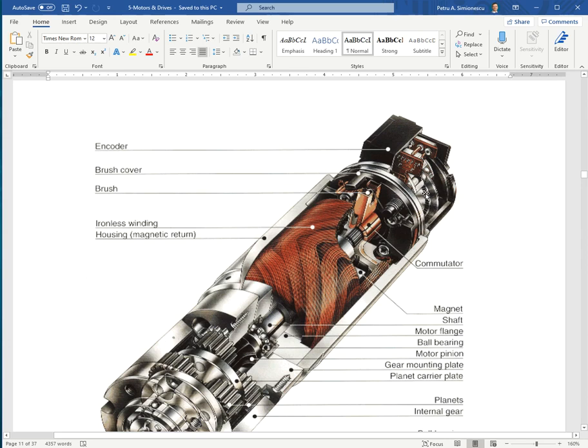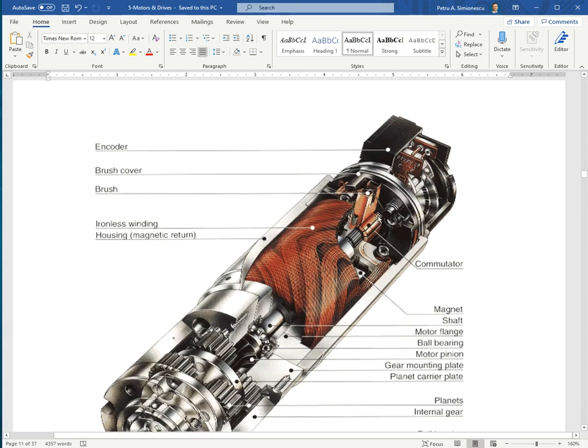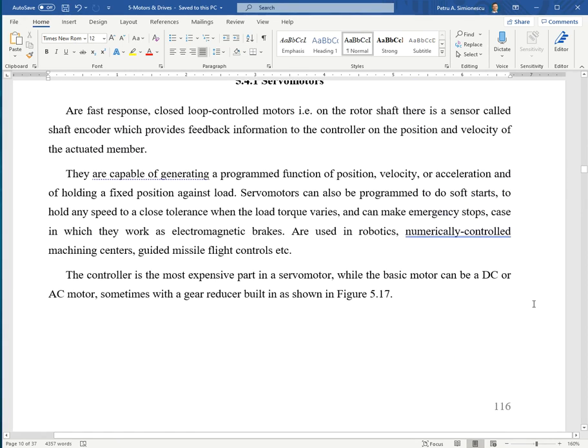You see only equally spaced slots that allow light to pass through, and it counts pulses of current recorded by a photodiode, and by counting those, you know how many turns, or fractions of a turn, the rotor shaft did.